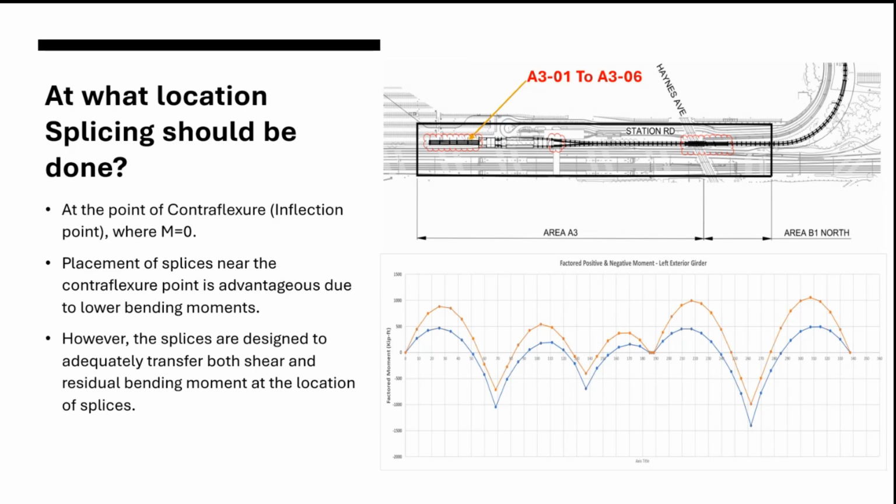Obviously, you look at your span considerations. If your span is like 200 feet, you definitely need a splice. So you would put a splice around 120, depending again on where your middle support is. Obviously, like Mansur said, you would not put your splice at the mid of the span or at the support. So you would try to see it would come out around one third, one quarter of a span in the first span or second span, and you assign your splice location there.